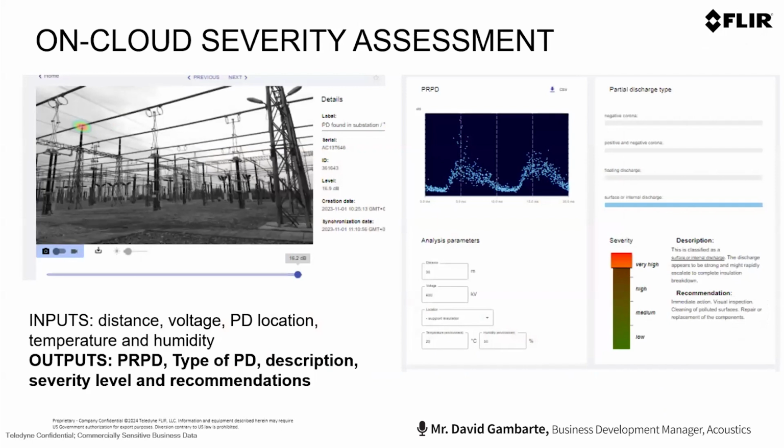So we talk about the on-cloud severity assessment, as you might be familiar with. I just wanted to mention we have in the cameras, of course, the severity assessment on the screen, and this is a very good feature for taking quick decisions on some partial discharges that need attention, right? For example, this one in the example here could need quick attention because it has very high severity, so it's a bit critical.